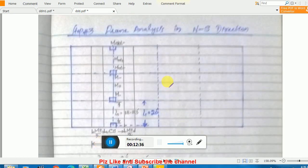So this is now step number 3, frame analysis in its direction. You see the interior frame is selected, L1 is now changed, and you clearly see L1 is your 20 feet. That is the center to center distance, because our direction of analysis is now north-south.